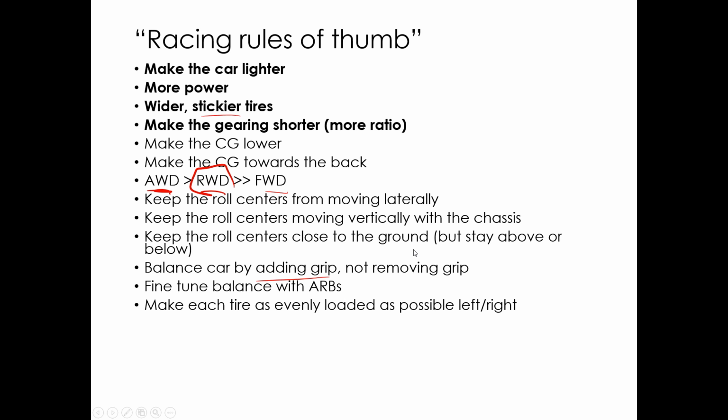Make your tires as evenly loaded as possible, left, right, fore, aft. That matters a lot. I mean, it's a fairly subtle effect, but once you've got something designed, it matters. Control camber. Again, fairly subtle effect, but you want your tires tipped slightly into the turn, depending on tire construction, usually 1 to 3 degrees or so.